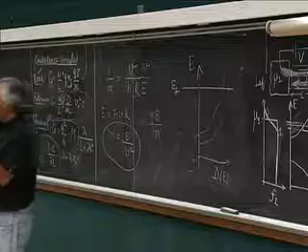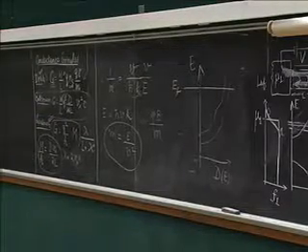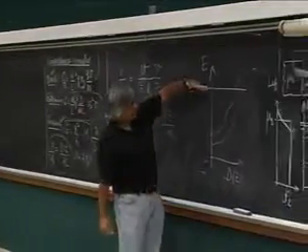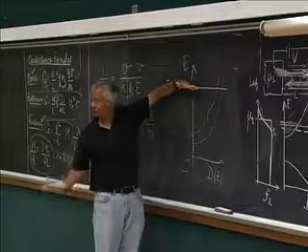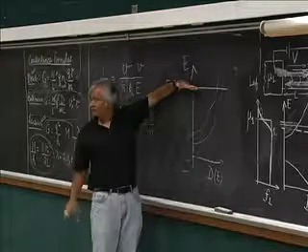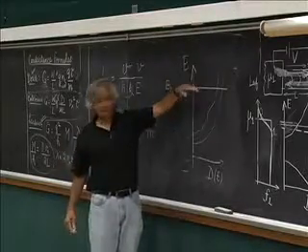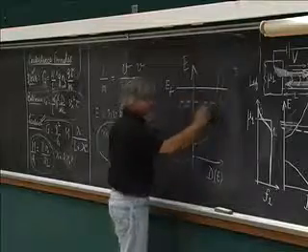If this was under a gate where you put a positive voltage, it makes it much easier for electrons to get in, all the electron energy levels go down. And if the electrochemical potential stayed right there, there would be a lot more electrons, which won't happen. Usually it would want to stay neutral. And so just as this goes down, the entire level will go down somewhat.